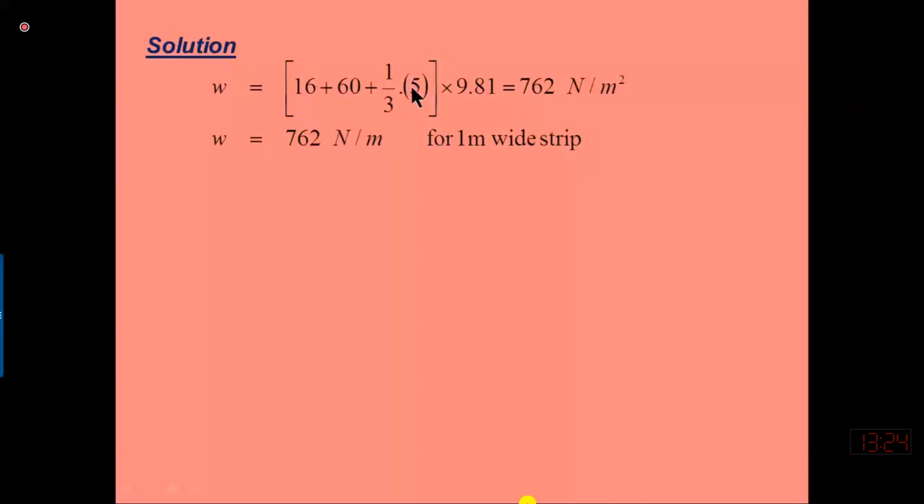A lot of connections, bolts, and washers are provided with the truss. We may be using only partial bolts or washers to connect the roof sheeting with the purlin. So the miscellaneous load acting on our steel sheets will be maybe 1/3 to half of the miscellaneous load.